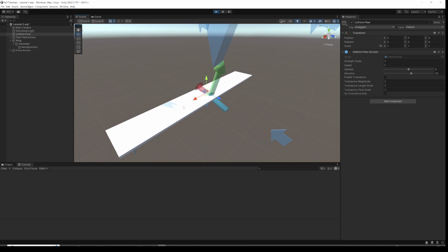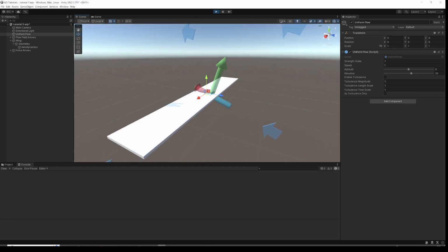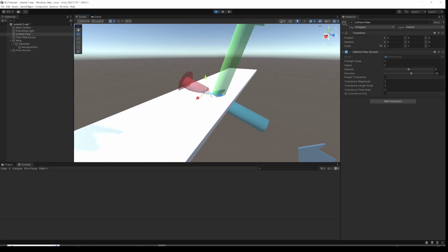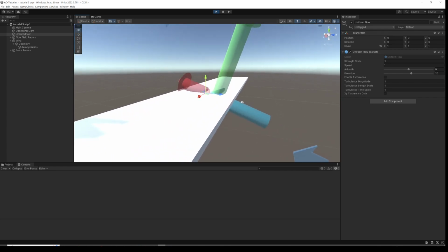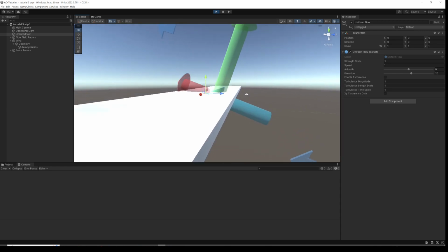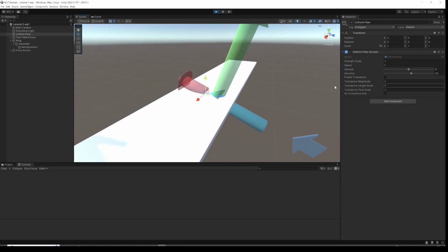If you imagine we've got a pressure distribution on this wing, it's kind of where, if you added up all the pressure, where would you put your finger to balance it? So that's where the lift acts. And from wing theory, at low angles of attack, you would expect the aerodynamic centre to be around a quarter chord. Let's reduce this down to 10.